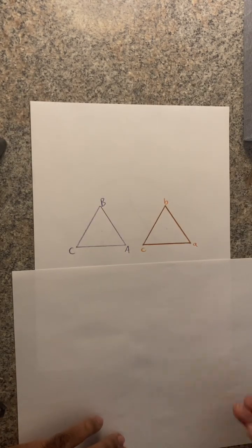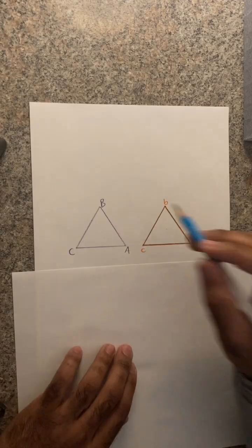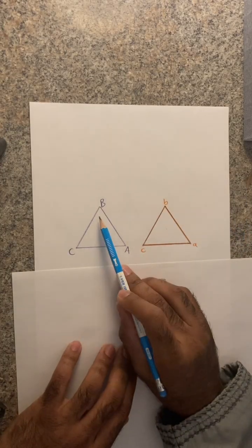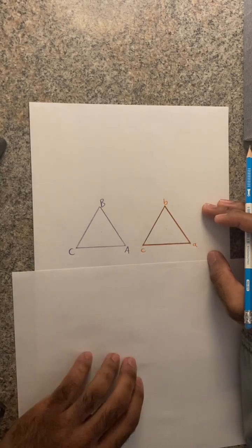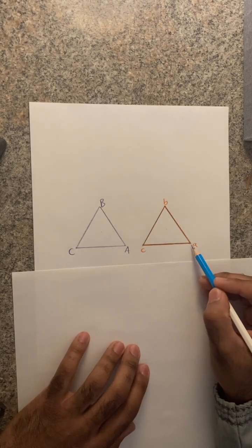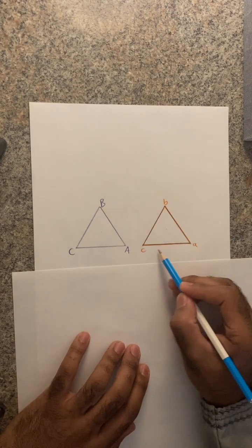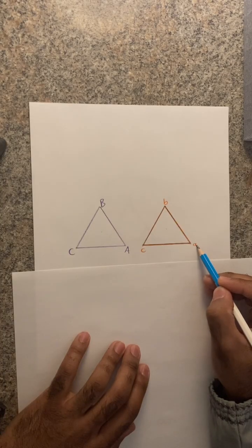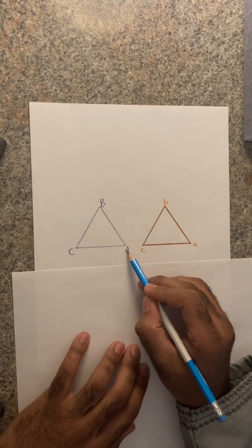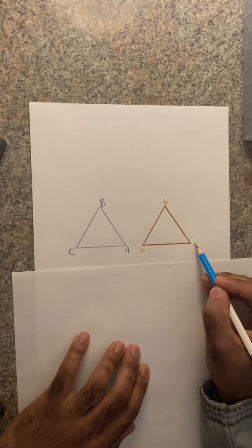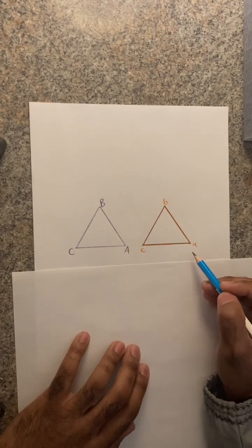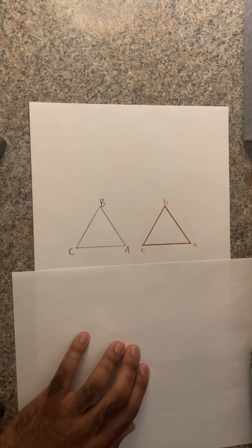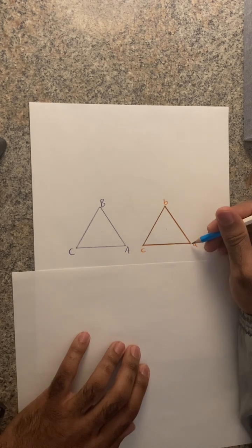But I will explain it further here. How is it that the displacement between a delta is 0 degrees? Well, that's obvious. That is because if we look at the position of A and the position of A on the secondary with respect to the position of A on the primary, we see that it is in the same position. Therefore, we consider this to be 0 degrees displacement.